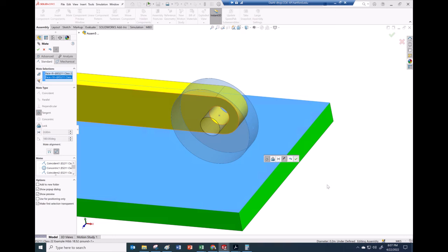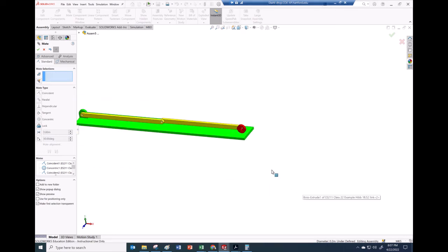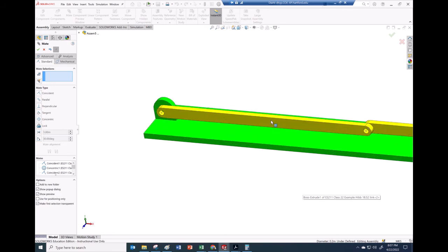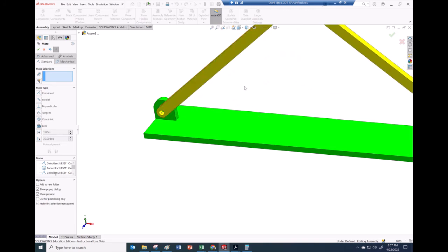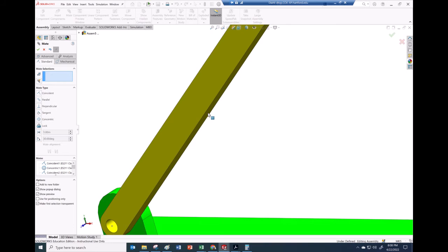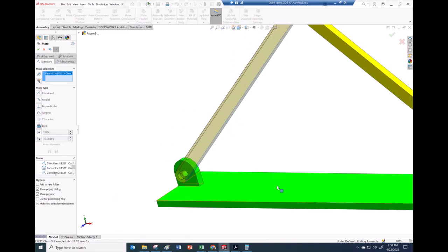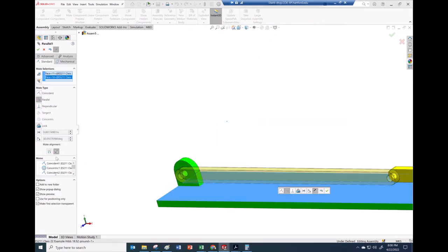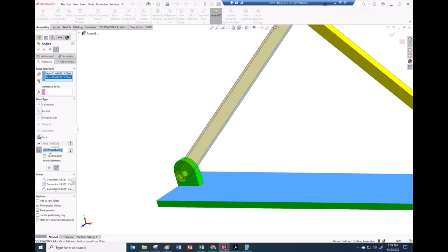And then the last one, I purposely made it the last one because I'm going to suppress it when I go to make the dynamics, to see if I can lift this up some. Then I'll make the angle formed between that bottom and this. It'll first try to make them parallel, but I'll come over here and click on that angle and make it 60 degrees.